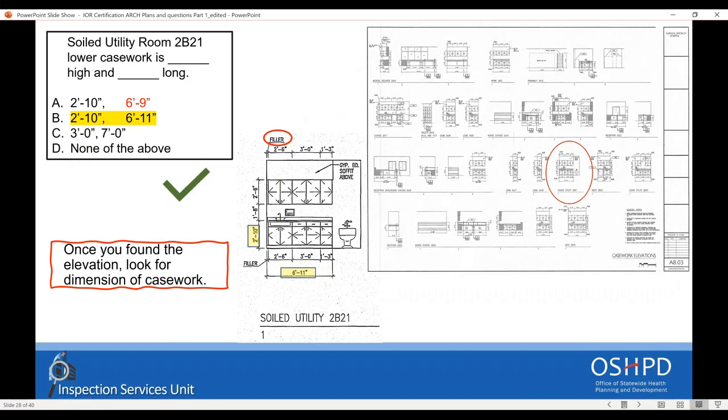And here you can see the dimensions. But pay attention to the question and to the information provided. It happens that people misread the information. They don't read the plan properly. It is instinct to just add the 2 feet 6 inches, the 3 feet, and then 1 foot 3 inches, and that will give you 6 feet 9 inches.